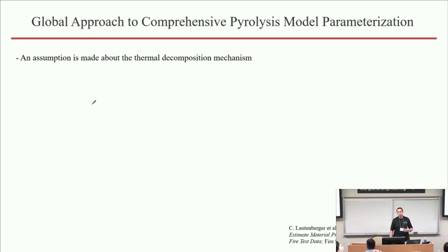In other words, you take a set of fire calorimetry experiments, such as cone calorimeter, but unlike in the previous case, we only had a couple of parameters that you can easily fit into this general data. Here you fit the whole curves as generated with these parameters that you define in this model.